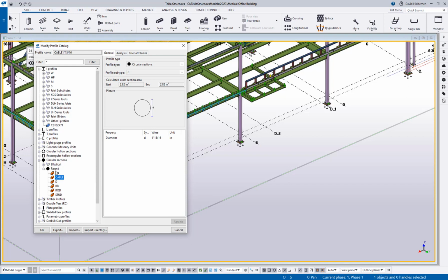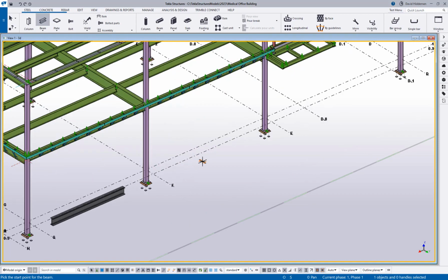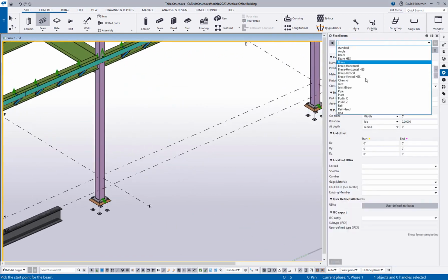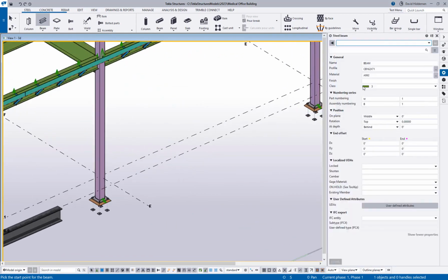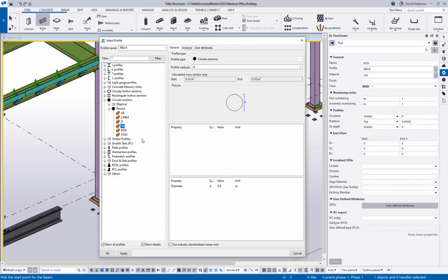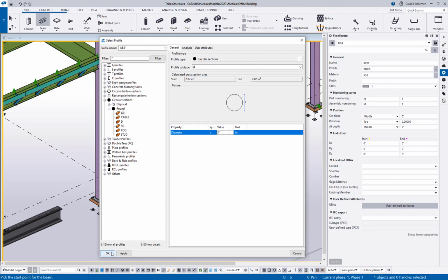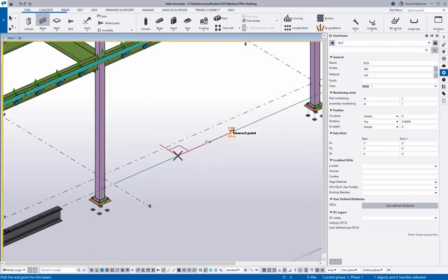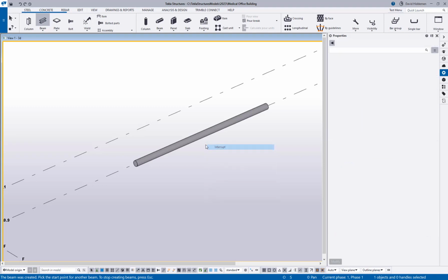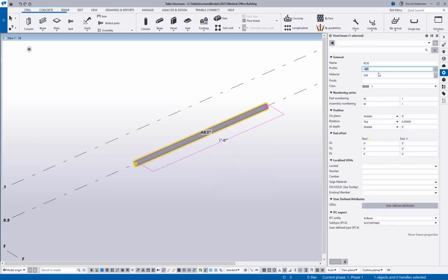So if I wanted to make an AB for an anchor bolt and I want this to be 3 inches in diameter, when I go to model in this part, let's go back over here and I'm going to load a sample rod profile. If I wanted to make that AB 3, as I was mentioning, I've got a now 3-inch diameter anchor rod. Or if I wanted to change this to be 1/2 inch, now I have a 1/2 inch anchor rod. So a parametric shape allows me to type in whatever I want.